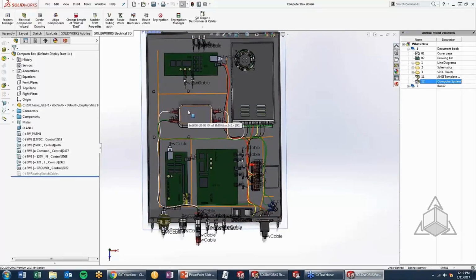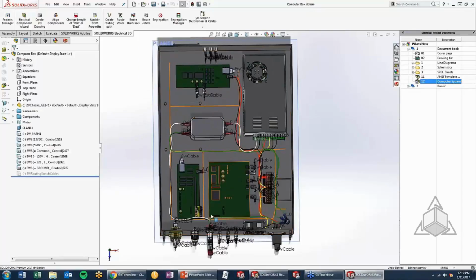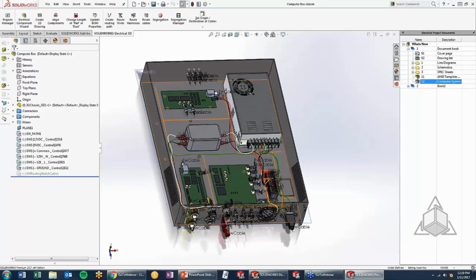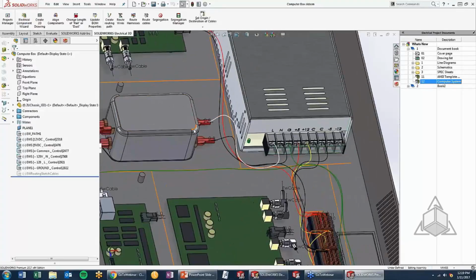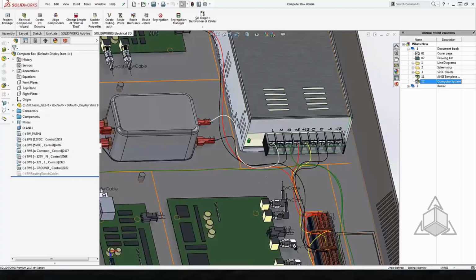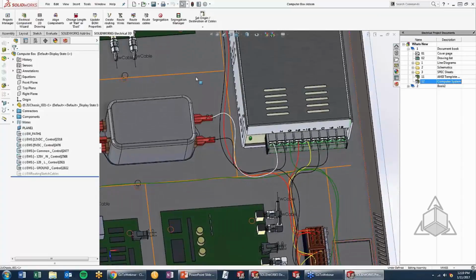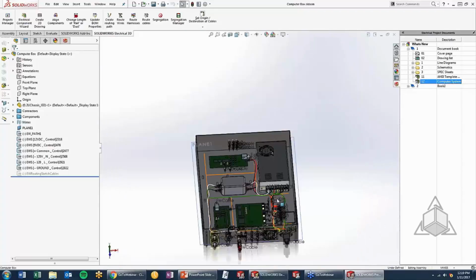All right. For those of you that are new to SOLIDWORKS Electrical, just an idea of some of the links that occur. Your components end up with connection points, so a C point that's linked to your terminal or your circuit and terminal information of your schematic, and we can generate wires, and these are just sketched wires that will follow a path inside of your assembly. So the orange line here is my path. The white, black, yellow lines are the actual wires with length and property information that get plugged into the system.